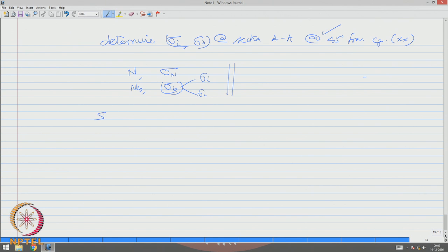So, friends, in this lecture we discussed the method to estimate bending stress in a circular ring. Rings and chain links are common in mooring lines. So, in mooring line analysis under special loads, you need to understand how to estimate stresses using the curved beam derivations that we discussed in the last lectures.